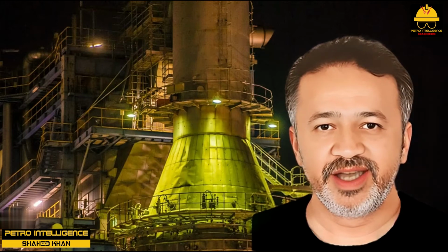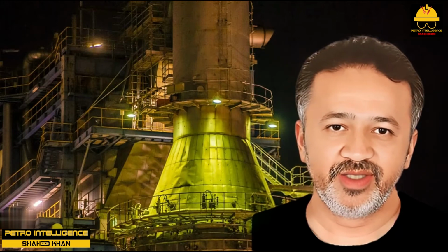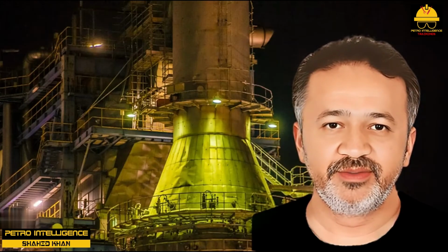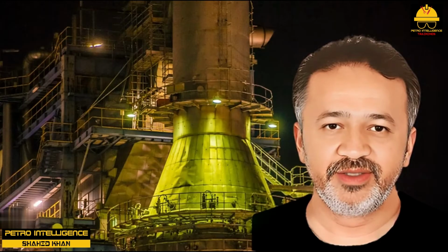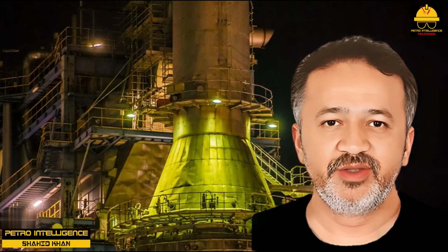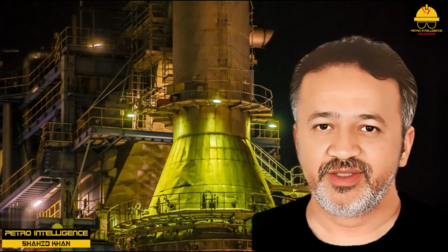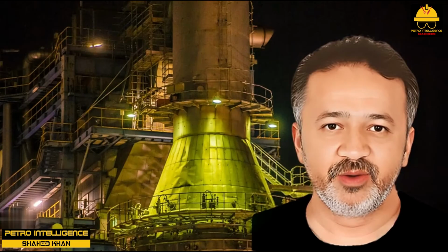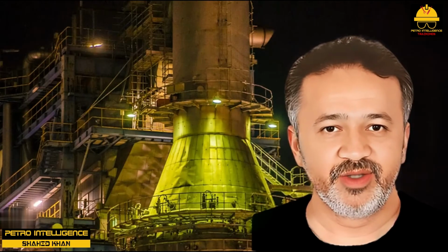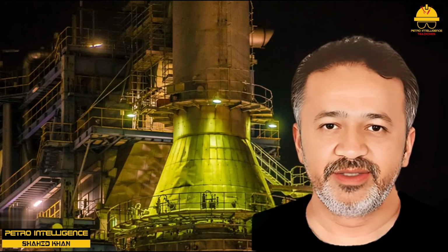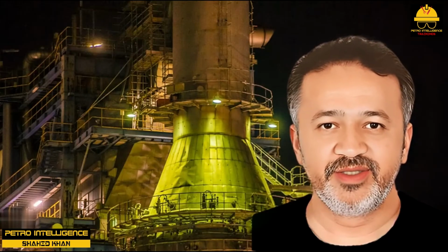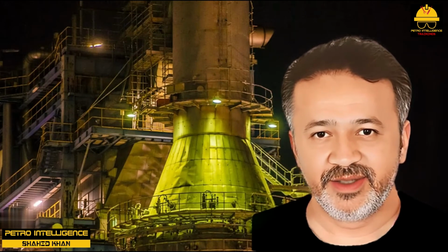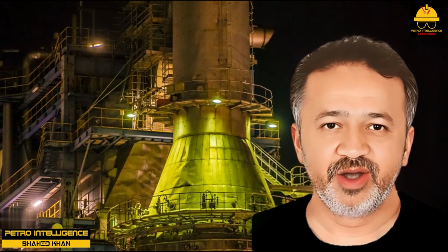The outside operator, Operator B, went to check on the firebox and, seeing that it was full of long, licking, yellow, smoky flames and had taken on a very hazy appearance, reported back to Operator A that he considered the amount of air in the firebox insufficient. Meanwhile, Operator A looked again at his O2 analyzer output, which showed 7.5% O2. He told Operator B that there was plenty of oxygen because the analyzer showed 7.5% O2, so he must be mistaken and, in fact, that he needed to pinch back still further on the air register to cut back the combustion air.